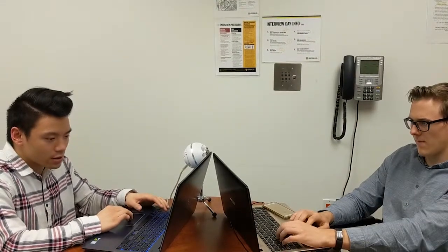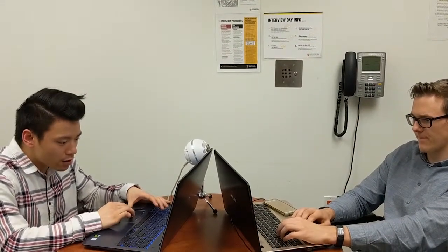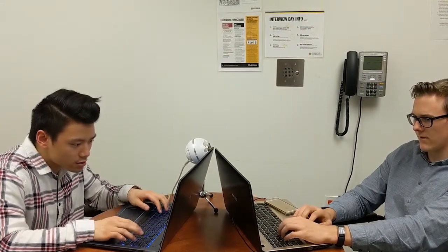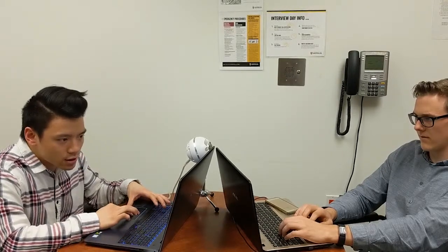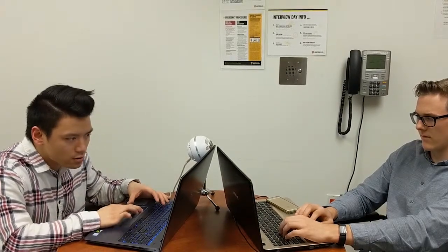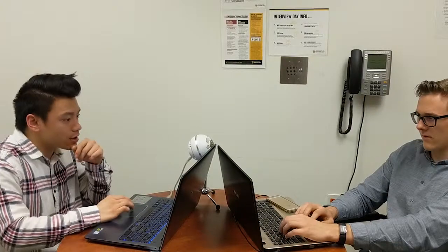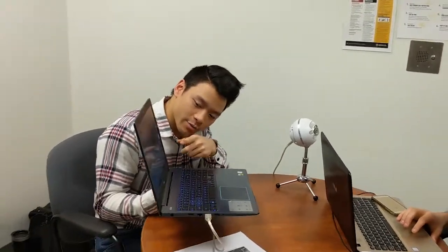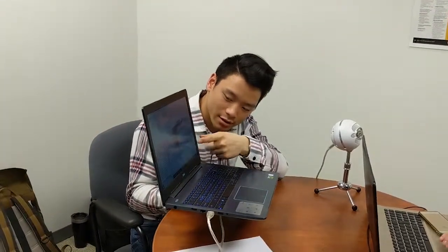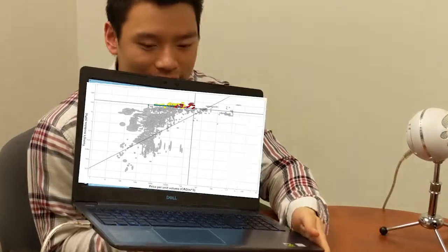Okay. And then if we plug those two in to make an MPI line, that should give us these lines over here. And cool. So I loaded it up into the CES like you said, and I got these three lines for the minimum Young's modulus, the maximum cost, and the MPI line.